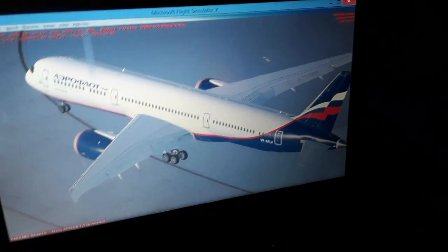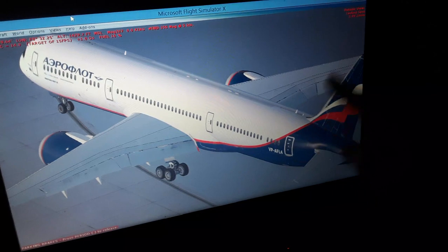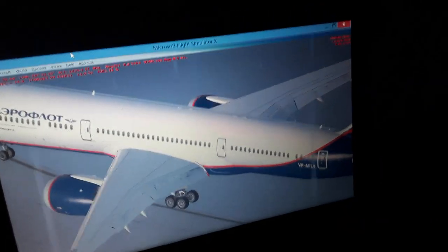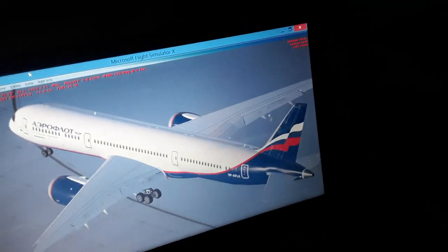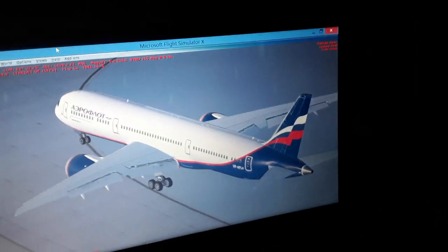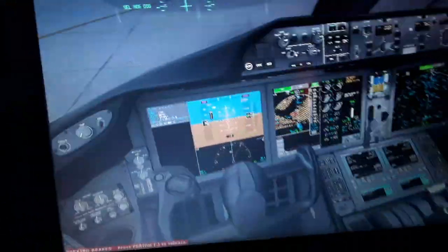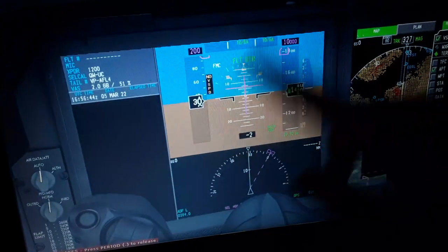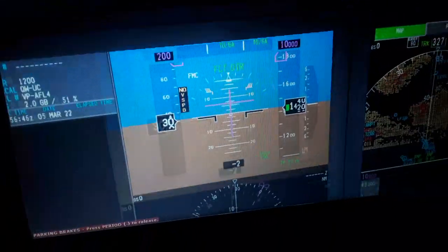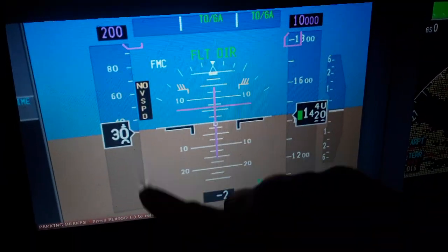detached from the top surface of the wings, and the aircraft goes into stall for a given angle of attack and airspeed in flight. So you need to monitor over here on the primary flight display. You need to monitor that the airspeed is correct, above your stall speed all the time. So you will see the stall speed with a number and red indication down here.